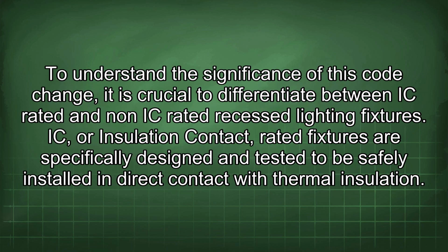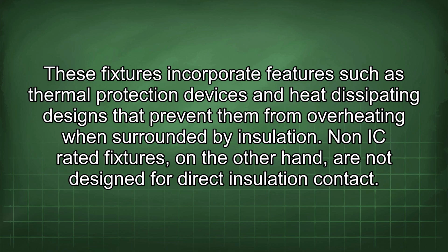To understand the significance of this code change, it is crucial to differentiate between IC rated and non-IC rated recessed lighting fixtures. IC, or insulation contact, rated fixtures are specifically designed and tested to be safely installed in direct contact with thermal insulation. These fixtures incorporate features such as thermal protection devices and heat dissipating designs that prevent them from overheating when surrounded by insulation.